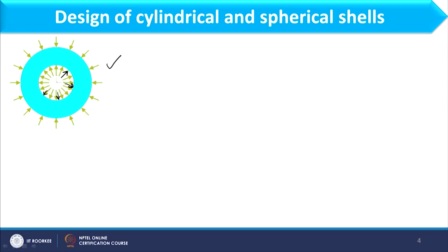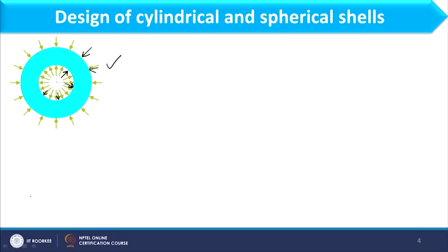Internal pressure, if you consider in this image, will try to expand this periphery. However, outer pressure or external pressure will try to squeeze this outer periphery. So both pressures are acting, and this condition would be the extreme condition which can ever occur in a pressure vessel design, and therefore we are starting design from this stage only. Now, to derive the expression for thickness of thick walled vessel, in this image we will consider a small section, and around this small section we will make the balances.